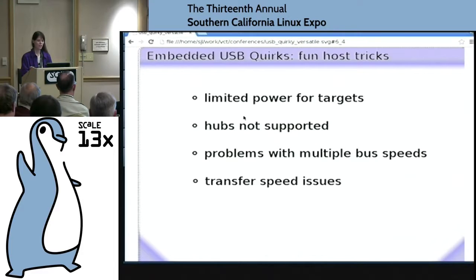But suppose you don't have a decent DMA controller, or suppose the vendor gave you a cruddy driver that maybe doesn't even enable DMA, then you're really hosed trying to do PIO USB on a USB 2 speed stream.